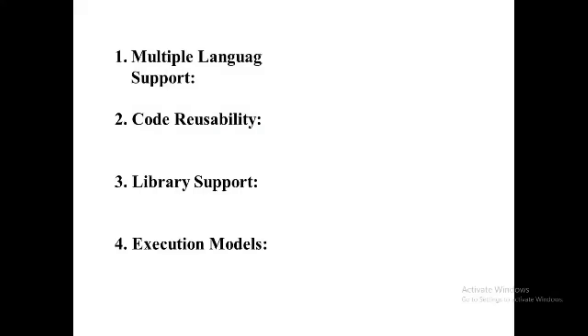As another illustration, Siemens has SIMATIC Step 7. This fully complies with the international standard IEC 61131-3 for PLC programming languages. With Step 7, the programmer can select from among various programming languages besides LAD and FBD. Step 7 Basic also includes the IL programming language.